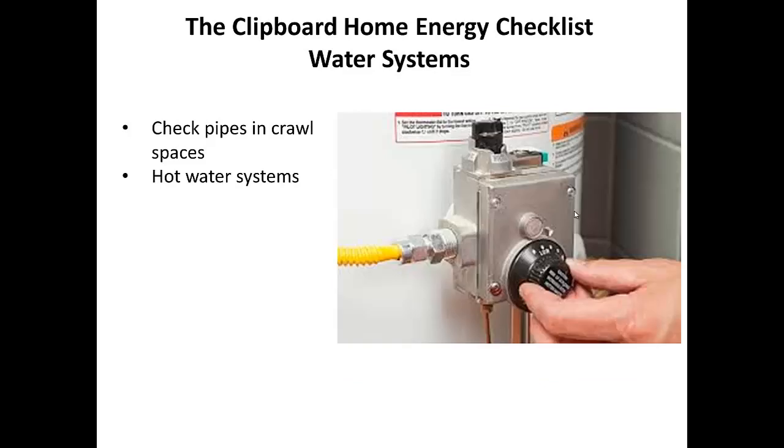For hot water systems, generally speaking, you want to set your thermostat to about 120 degrees. You have to kind of adjust it yourself and decide how warm you really need it. As cool as you can keep it and still have it warm enough, that's where you want it. I put it so it's a little bit too hot for me to have my hands sitting underneath it, but it's not going to scald me. And you're talking about your tank losses here from the surface of this tank.